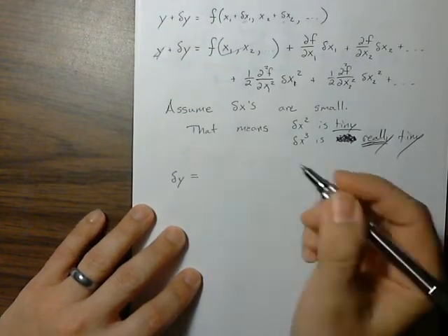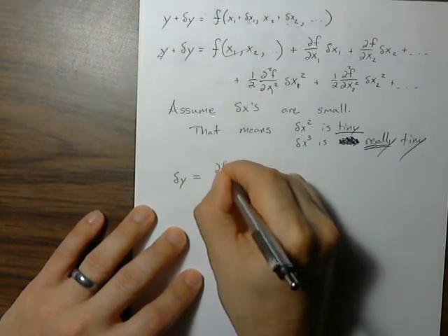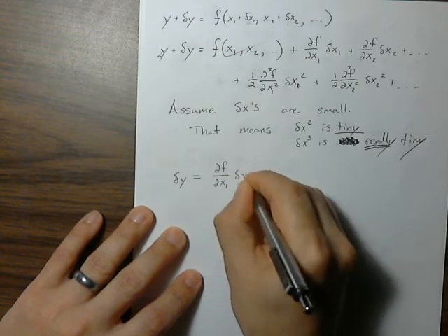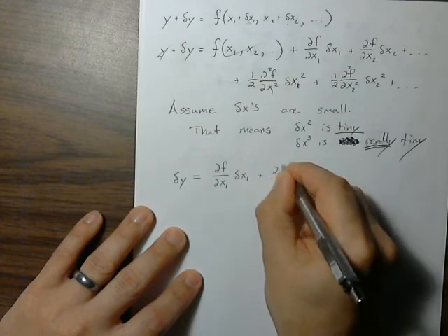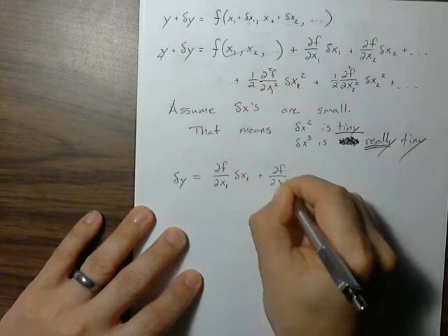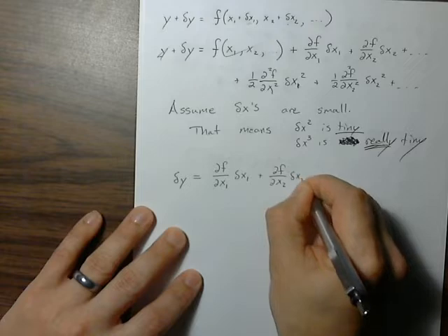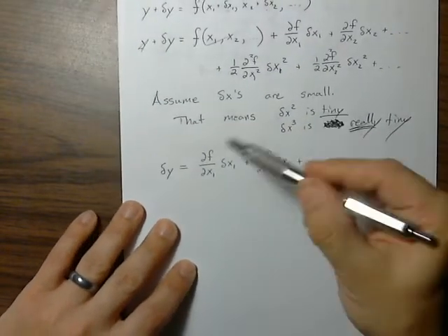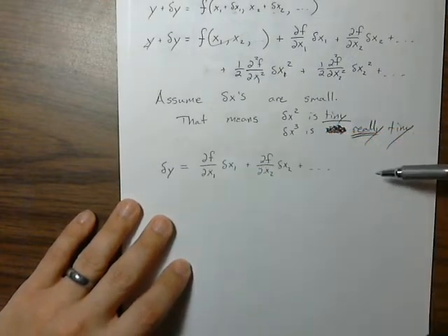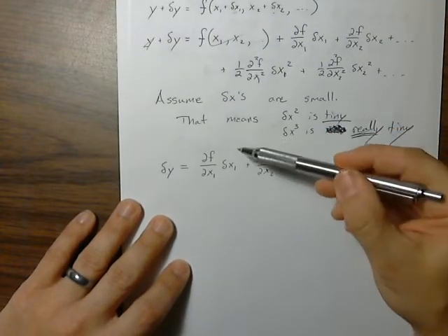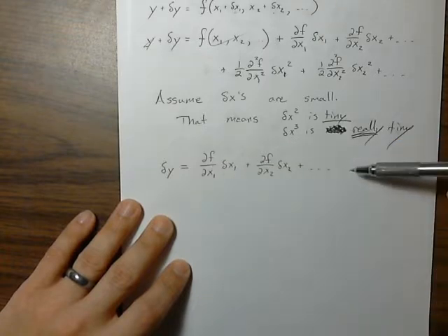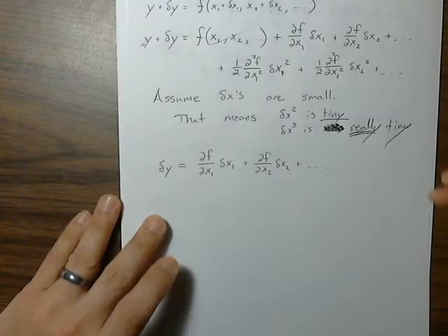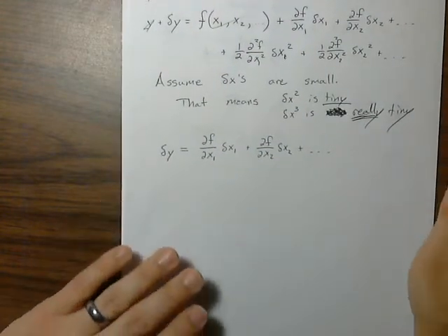Are, or well, is rather, just the dot dot dot. And you can just keep going. So however many input measurements you've got, you just take the partial derivative of your calibration function and sum up the effects, and that's the effect it will have on y. All right, so now we need to get to the business.